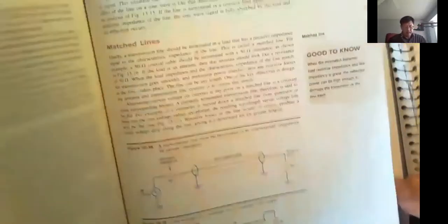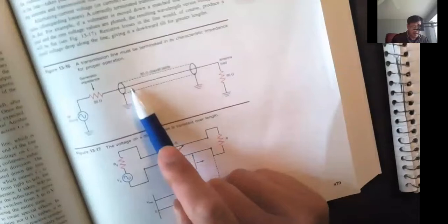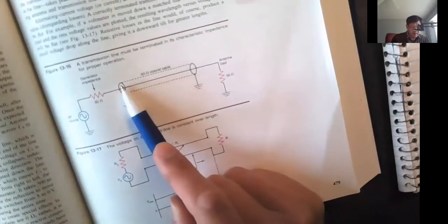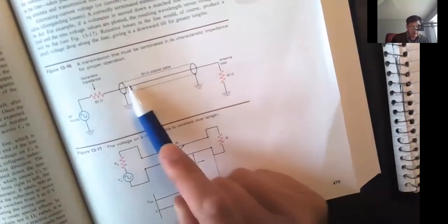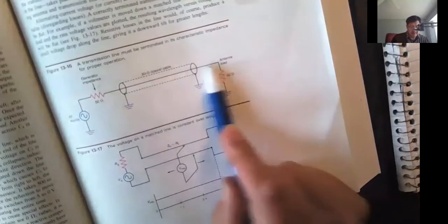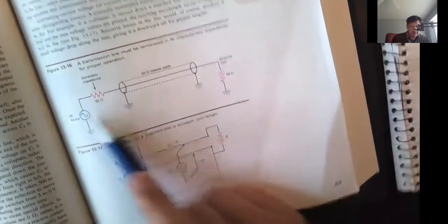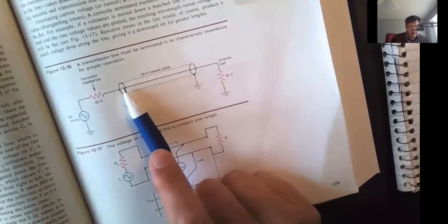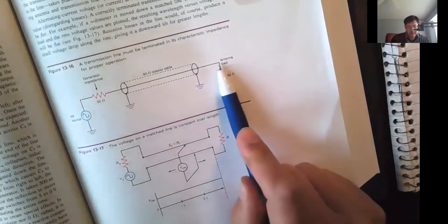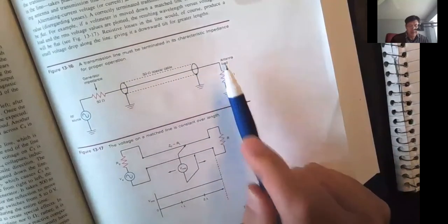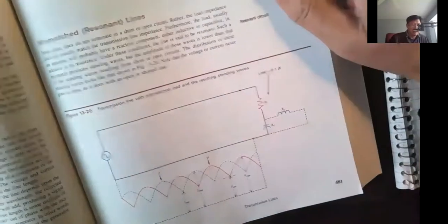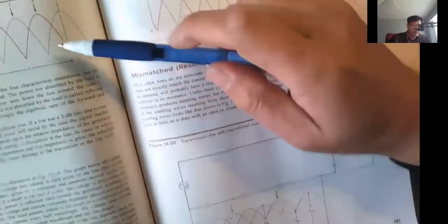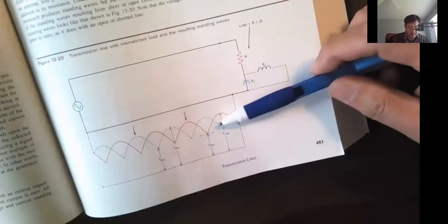Ideally, it will be the same, half the voltage. That's ideal. The voltage everywhere here is flat. There's no standing wave. That's the ideal scenario. But in most cases, the non-ideal scenario, when you measure the voltage across the transmission line, you get the ups and downs. And those ups and downs are called the standing wave. So that's one case, another case, and another case, the standing wave.